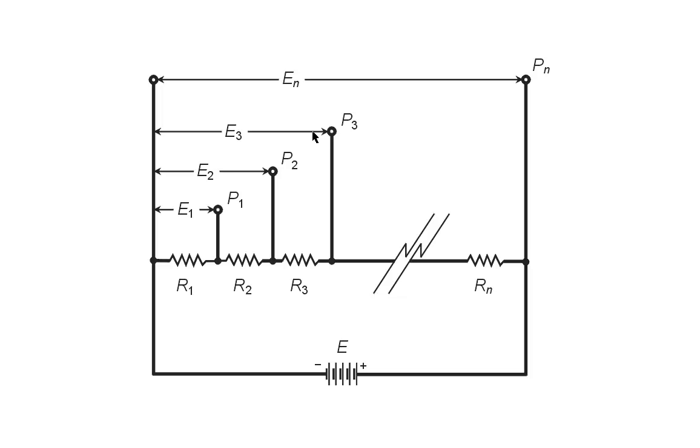But if we put, say, a 6 ohm load across this 9 ohm resistor, or to make it more simple, a 9 ohm load across the 9 ohm resistor, we're going to change this R sub 1 all the way down to 4.5 ohms, and that's going to throw off the entire voltage divider network. So it's important when you design a voltage divider to keep these resistances a lot lower than you expect the loads across them to be. Otherwise, you're not going to get the values that you're hoping for.